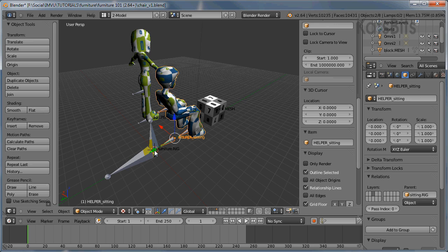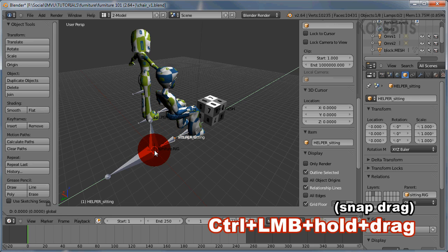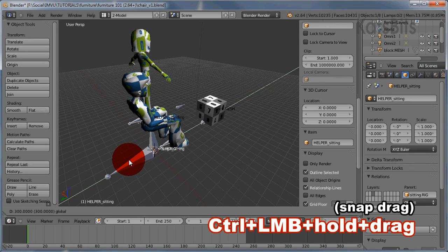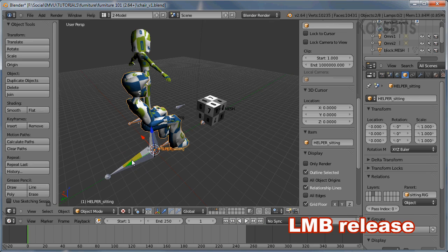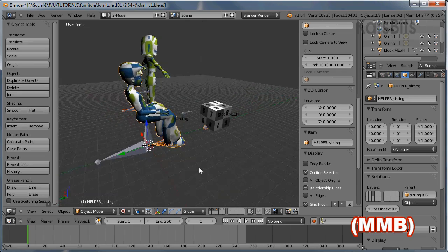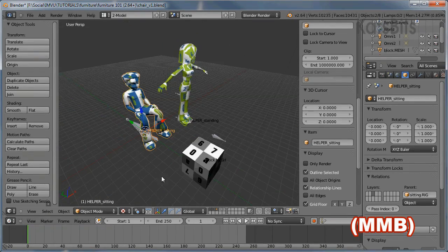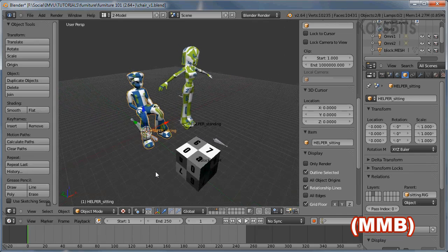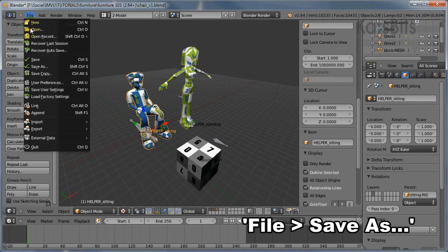Do the same thing again on the green arrow, left click hold, hold control down and drag back so that that little dot is on the intersection between the red line and the green line. So release the left mouse button and control. So we've got a green axis indicator and a red axis indicator, and they intersect where this small dot is. But for now what we've done is positioned the avatar helper in a way that's going to help us make the chair.